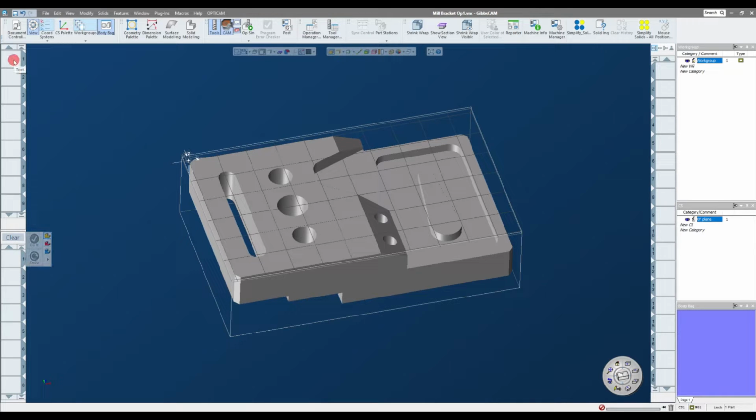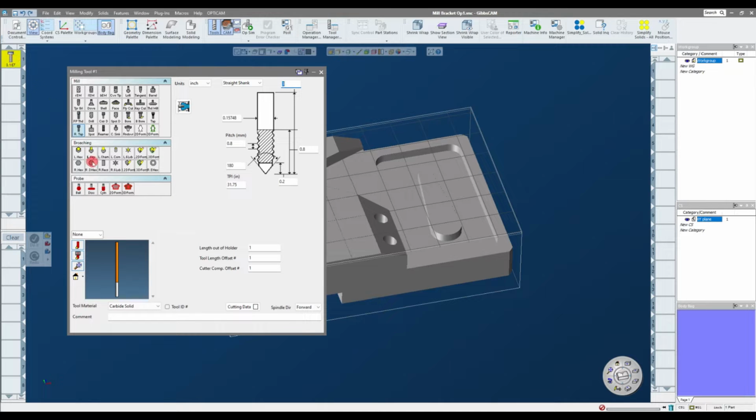So in this particular instance, I'm going to double click in this first tile. And you get all the list of tools, broaches, probes, if you have the probing operation for GibbsCAM, that you're going to create. So for this one, I'm going to create a shell mill. I'm going to tell it it's 1 inch diameter. Let's call it a 7/8 shank. Corner radius, let's give it a 30 thousandths corner radius, and maybe a 1/2 inch insert length. Just a very generic tool.